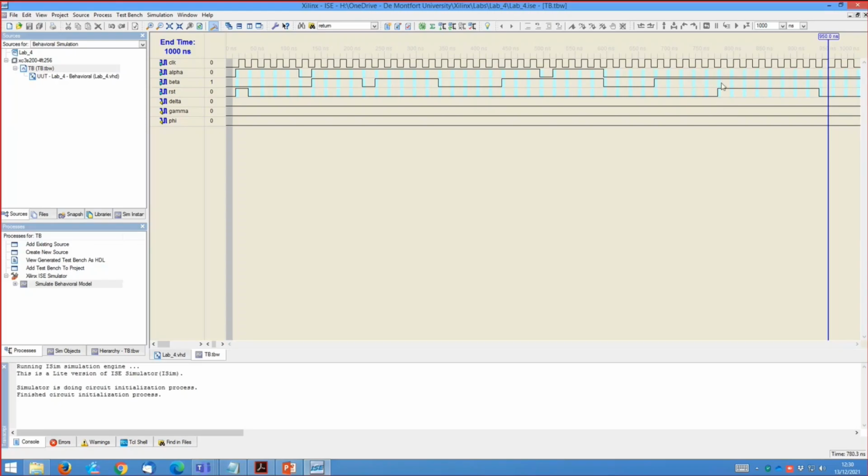The last thing that I've done here is to have an extended reset period just to see the reset operating during a couple of clock cycles to show its asynchronous nature. So I've basically enabled reset there, and I kept it enabled for a bunch of clocks just to see it working. So that's pretty much my test bench and the reason why those signals were set like that.